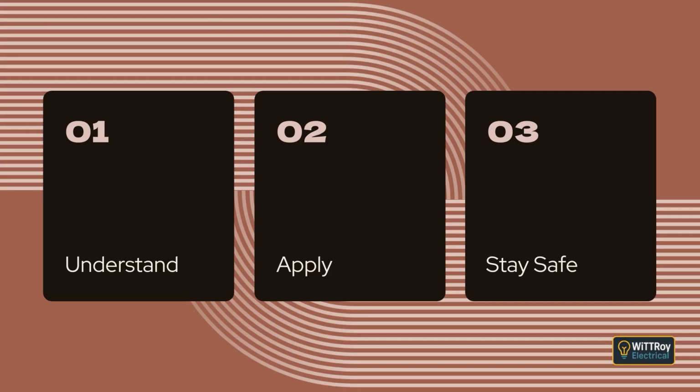Clause 3.9.9.2 Precautions. Wiring systems must be installed so the building's structural performance in a fire is not reduced. Cables and wiring products with appropriate fire ratings must be used where required. Wiring systems that do not meet the required fire rating may be used only for short lengths when connecting appliances. Segregation between fire-rated compartments must not be compromised.